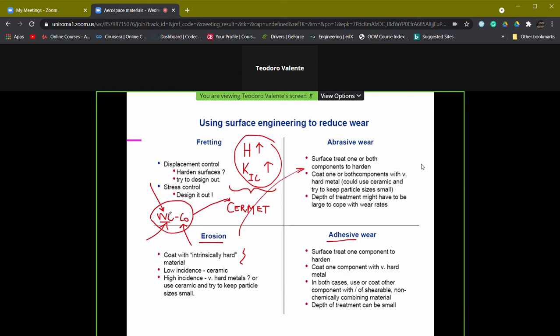And most of the time, apart from the solution that now we should know very well, having talked about it many times, of coatings in terms of thermal barrier coatings for gas combustion chambers and turbine blades, for example, the solution to overcome corrosion problems or tribological problems, let me say at standard temperature, not high temperature as in engines, needs to be considered together, because we can have both phenomena, and they can be synergic, and so solutions must be defined which reduce the severity of both, thus increasing the expected lifetime of our components.